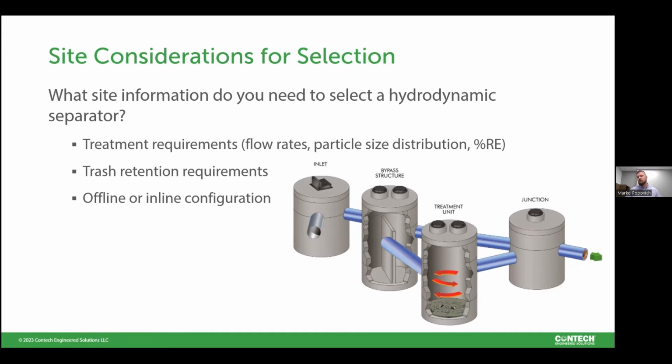The other two considerations to have here would be trash retention requirements. Do we need to make sure all floatables, anything larger than 5 millimeters, is captured and retained within the structure? And then ultimately, does that treatment technology have the ability to bypass internally, or do we need to move that offline?